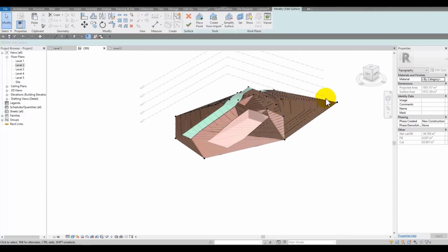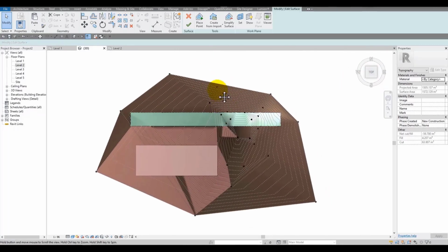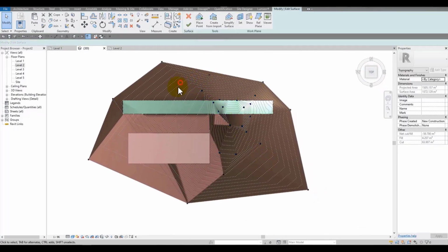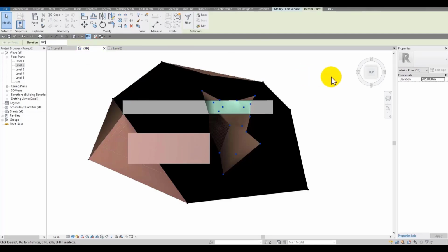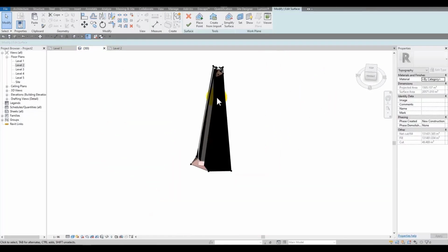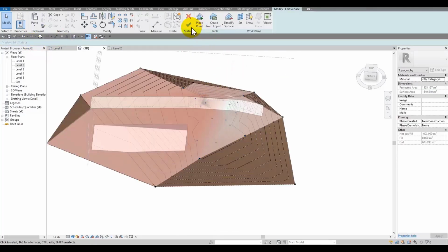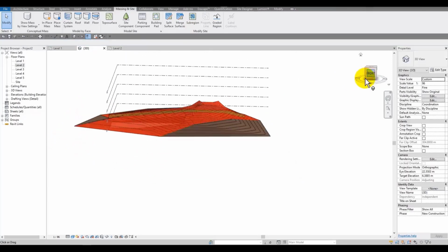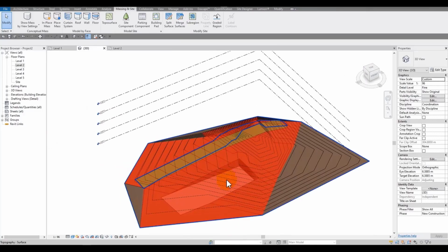And when I select this and edit surface, here for example, I wanna have all of these points with different heights. The height here is 2.5. I wanna have all of them in 2.5. I think I entered 25 by mistake. Okay, I wanna have the whole area in this height, and as you can see in this view, these are excavated areas as well.